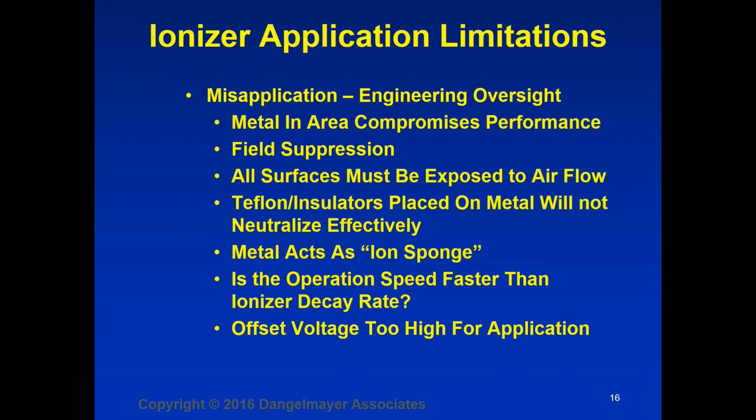Anyway, how about the application limitations for ionizers? What do we need to pay attention to? Most of the misapplications of ionizers tend to be through engineering oversight. And what we have here is a list of some of those things that you need to be paying attention to when you use the ionizer. First of all, a lot of metal in the area around the sensitive devices is going to absorb the ions, and it will compromise the performance of the ionizer.